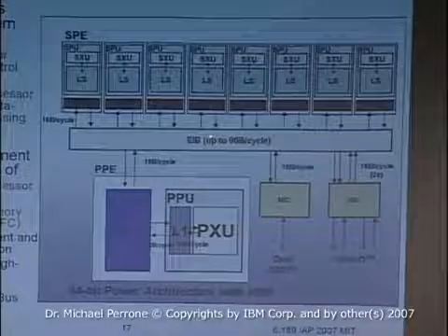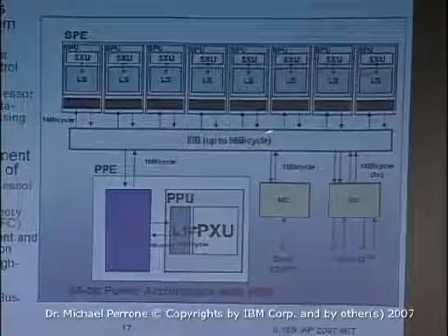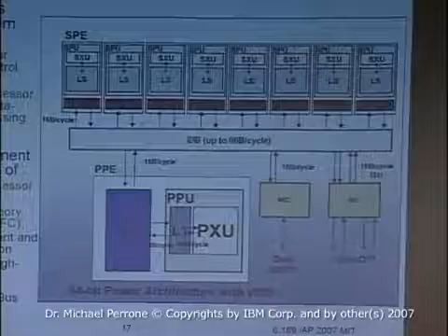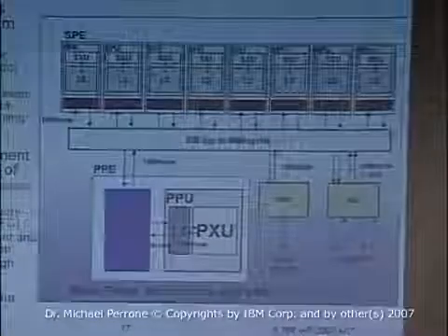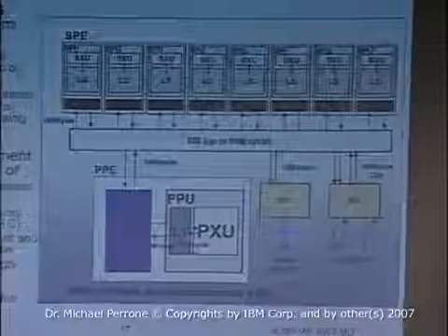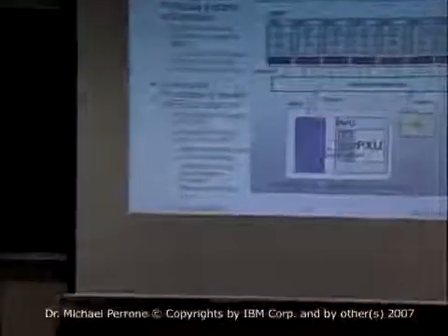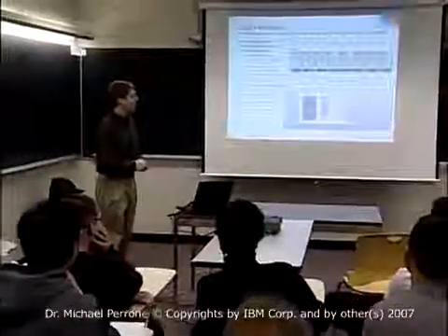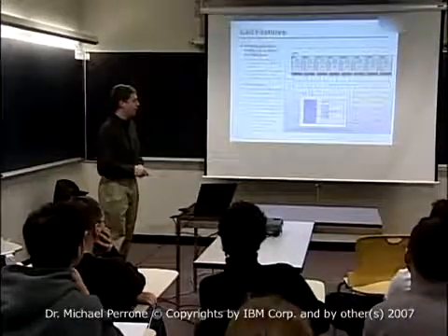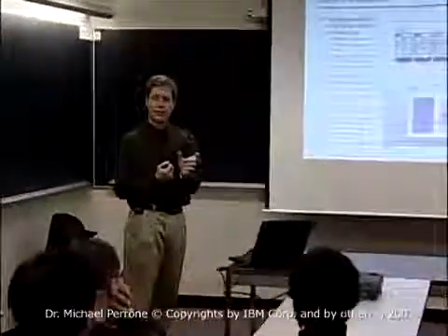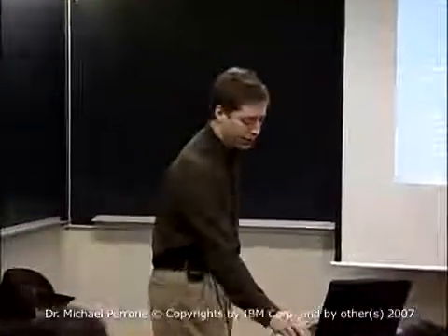gigabytes per second. These guys can communicate to one another across this bus without ever going out to main memory. And so they can get much faster access to their local memories. So if you're doing lots of computes internally here, you can scream on this processor. You can really, really go fast. And you can do the same if you're going out to the memory interface controller here to main memory, if you sufficiently hide that memory access. So we'll talk about that.